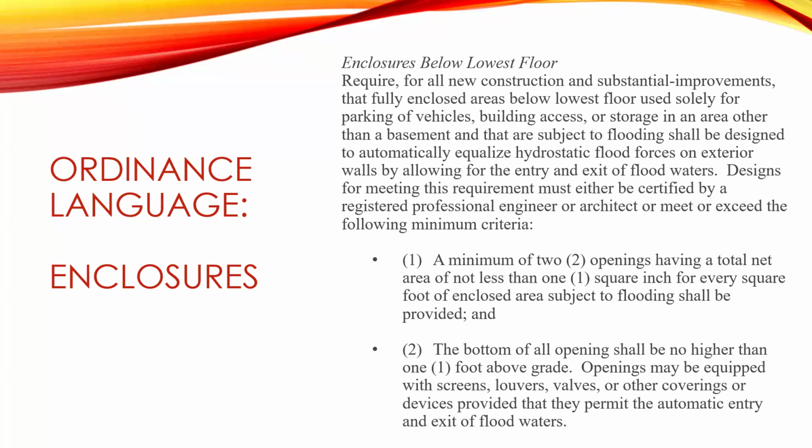So again, we're equalizing the pressure of the floodwaters by allowing them to enter and exit that area freely, and that relieves the pressure on the outside. Otherwise, you could have collapsed foundation walls, and that's structurally very damaging and very expensive. So that's why this is a requirement for those enclosed areas. And so we have these designs certified by a professional engineer or architect. So enclosures below the lowest floor, we're talking about either residential or non-residential structures. So that's a little bit different than what's required for the accessory and agricultural structures.